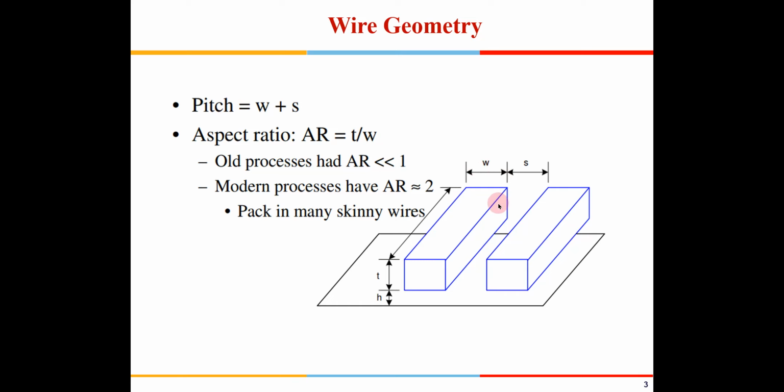The reason the minimum width is specified by each technology is that here it looks like a perfectly straight line, but when we actually deposit these metals, it won't be a straight line. There will be some imperfections on both sides, and catering for those imperfections, there should be a minimum width, otherwise there will be a break in the conductivity. Even with the worst case imperfections from both edges, there has to be good connectivity along the wire. That is why we always define a minimum width for a conductor.